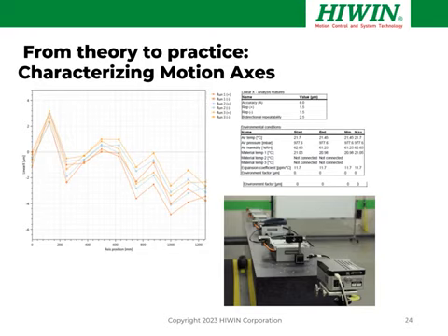It's a rather expensive but extremely precise instrument. It's using the wavelength of a laser light, which is very precisely known and is fully traceable back to NIST. And it gives you the positioning accuracy and the repeatability, but also by different optic designs, you can measure the other stage geometric errors. So you can measure those other degrees of freedom.